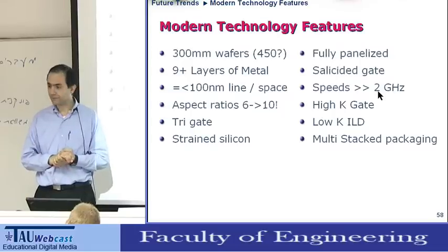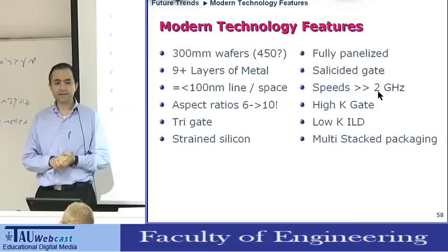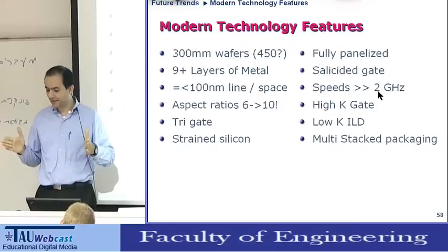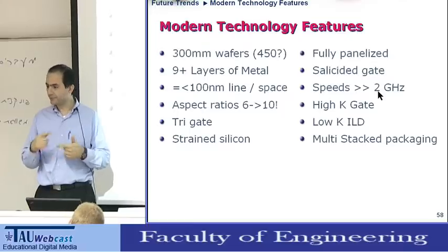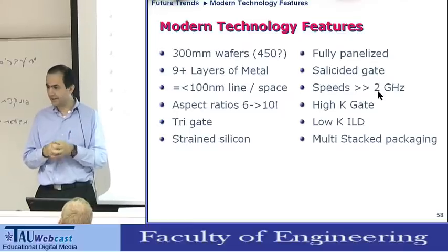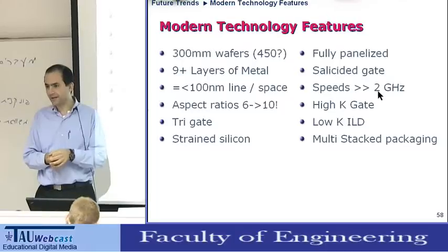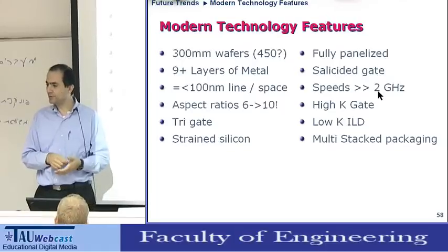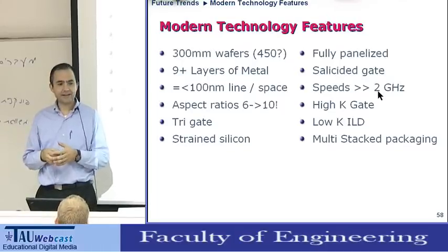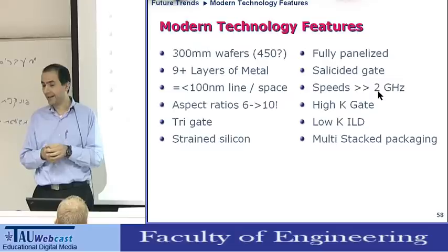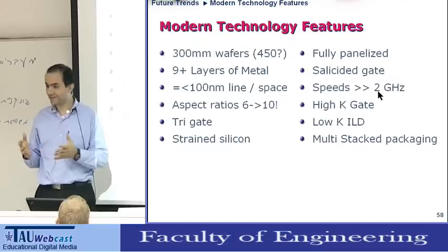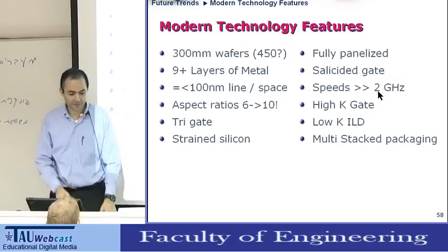So when we increase the frequency, the heat dissipation increases. And what happened is that we make the transistors smaller, we put more transistors, we increase the frequency, and we get more heat in a much smaller area. And if this trend were to continue, we would get, in a few years, an area which is hotter than the exhaust of a jet plane, and later hotter than the sun. So obviously this trend had to stop.